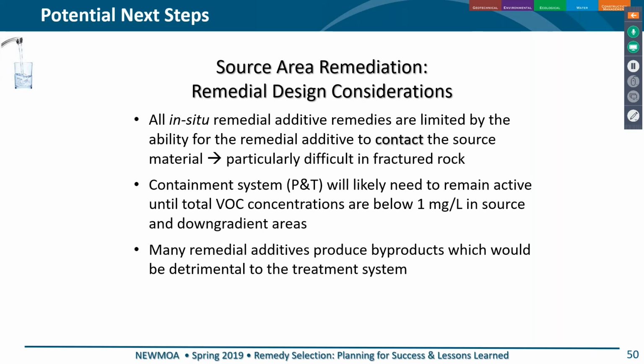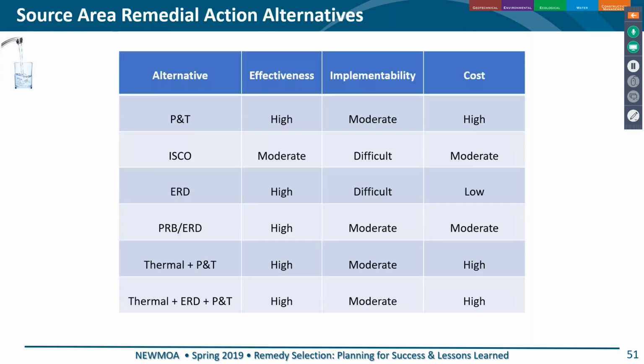We have a lot of iron in our rock, so you get iron in reducing conditions, low redox conditions. The iron becomes water soluble. You bring it up to the surface into your pump and treat system. Add some oxygen, it becomes a nice red slimy mess, and that's not going to help your treatment system. You're going to have to be doing a lot of maintenance. So, like I said,